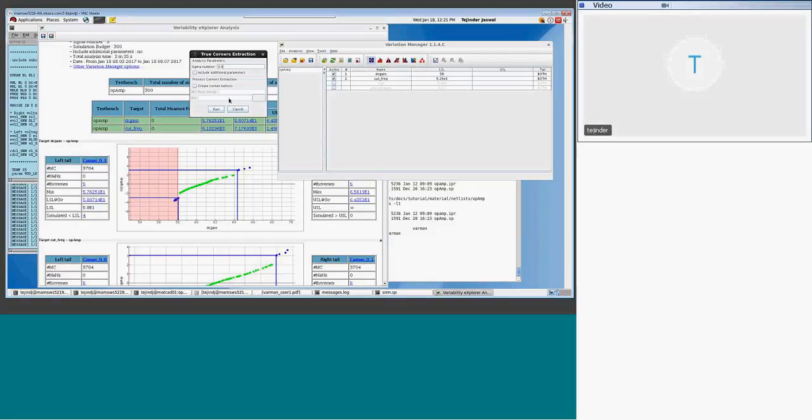TrueCorner is to be compared to PVT corners. PVT is global, but you can do true corners, so it's similar to PVT, but they are statistical corners. So instead of doing fast Monte Carlo at 10,000 or 50,000 or 3 sigma, which is more than 100,000,